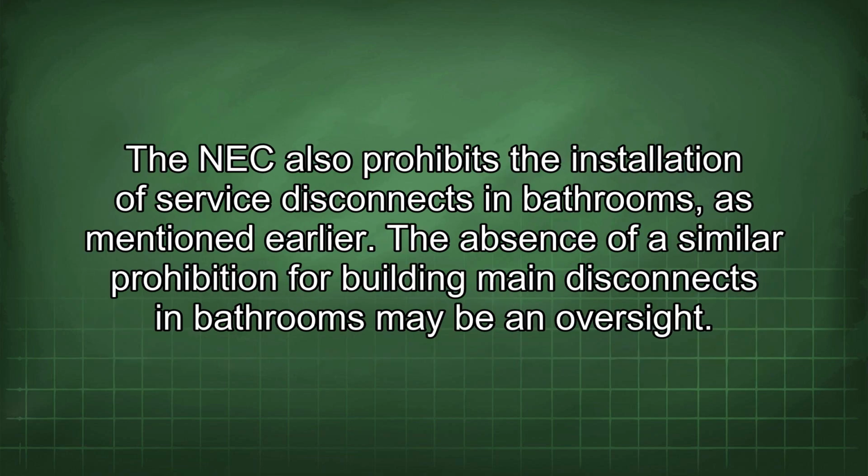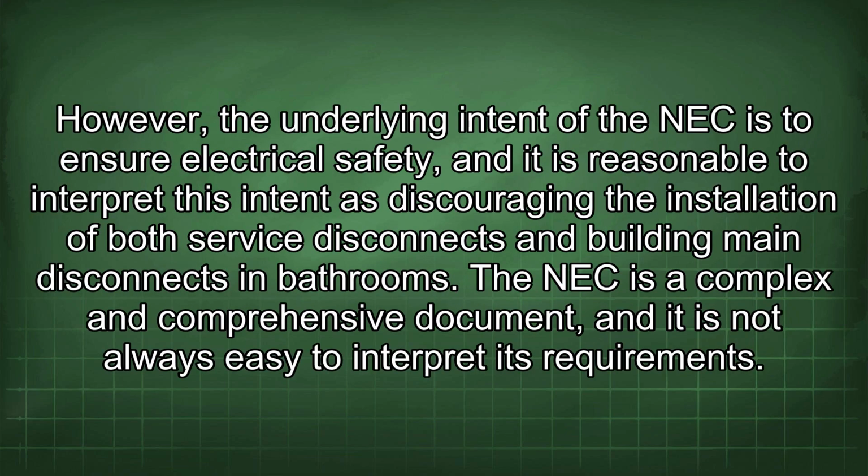The NEC also prohibits the installation of service disconnects in bathrooms, as mentioned earlier. The absence of a similar prohibition for building main disconnects in bathrooms may be an oversight. However, the underlying intent of the NEC is to ensure electrical safety, and it is reasonable to interpret this intent as discouraging the installation of both service disconnects and building main disconnects in bathrooms.